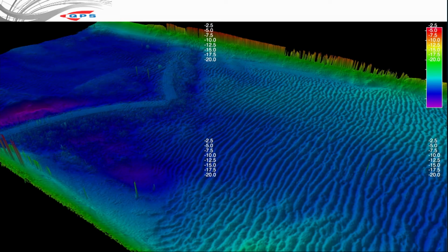But then I went ahead and said, okay, you're looking at gridded information here. So rather than looking at the mean depth within each grid cell, let's look at the shallowest depth, which is the way NOAA, the Corps of Engineers, several hydrographic organizations look at their data set, because in hydrography, it's not so much about the mean depth, but what they really want to know is basically what poses a hazard of navigation. It's always that shallowest data point. So when I bring that up, all of a sudden we start to see spikes in the data set, or anomalies, at least things worth investigating.